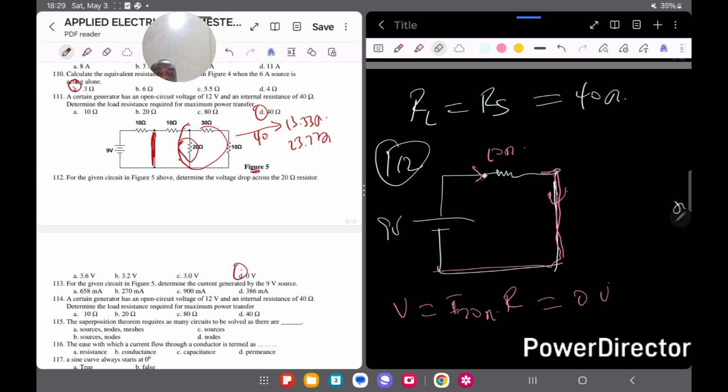So with this, we can see clearly now the current will just pass through this 10 ohms resistor, then pass through the wire, then this way. That's how the current will flow, just pass through this part. So now finding the current just becomes what? An Ohm's law problem. We get the current by taking the voltage, which is 9, and now we have only this one resistor here, so divide by the resistance, which is 10.